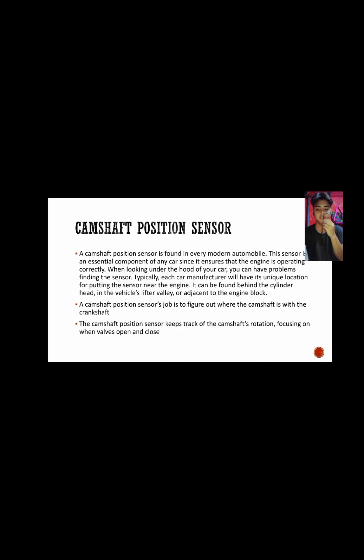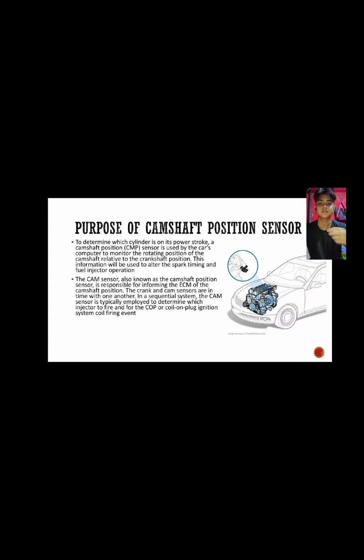A camshaft position sensor's job is to figure out where the camshaft is with the crankshaft. The camshaft position sensor keeps track of the camshaft's rotation, focusing on when valves open and close. Purpose of camshaft position sensor: to determine which cylinder is on its power stroke.